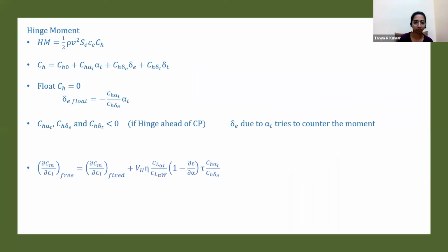Let's proceed. Just to go over the contents of week 7 prior to solving assignment 7. We've studied longitudinal stability and control. Longitudinal control is brought about by an elevator. The elevator is on the horizontal tail, so the lift produced on the tail produces a moment about the hinge.